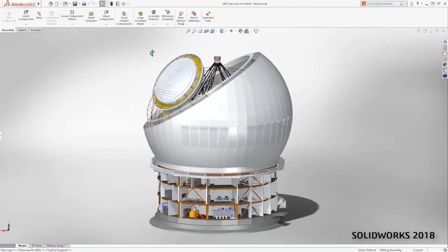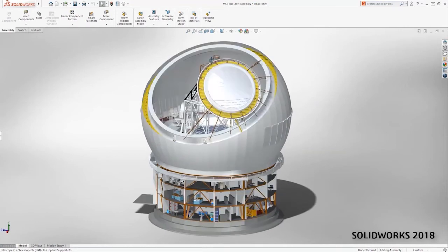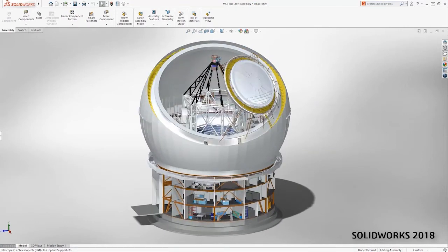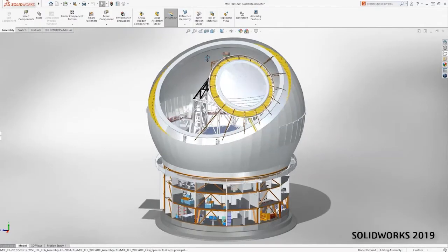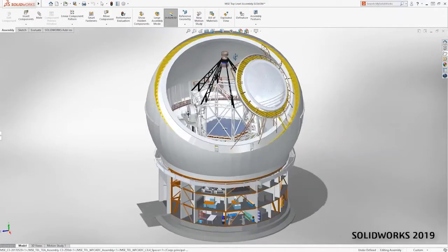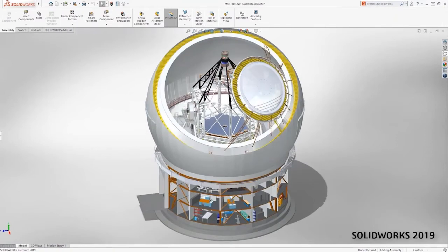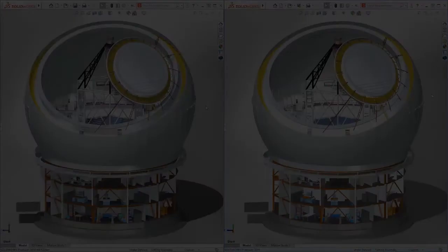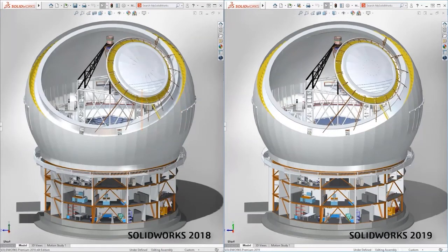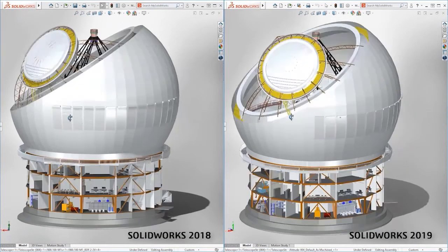We get great performance while we're moving, however. Turning large assembly mode off now, you can see that that performance quickly disappears. The detail comes back, we get great performance with the detail, but the actual movement is very slow. This is now a command that said set large assembly mode turned off. And it's almost exactly the same as working in SOLIDWORKS 2018 with large assembly mode on.